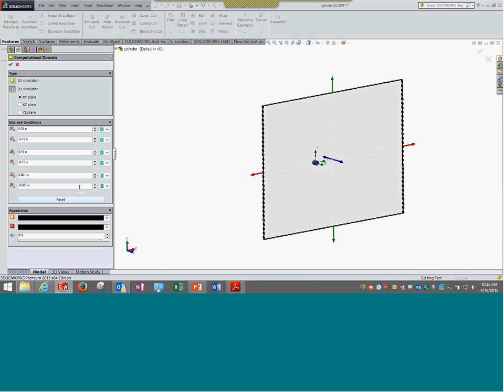And to represent it, we are giving a certain minimal thickness to represent the normal directional flow. Be aware that whenever we are doing 2D, the same logic that we discussed for simulation in terms of symmetry holds here. So we are assuming that there will not be any flow in the Z direction. It would always be in the XY plane. Normally there is no turbulence, there is steady flow, and it's almost zero. So that is a big assumption that has been made here.